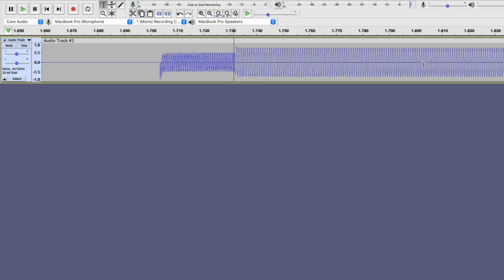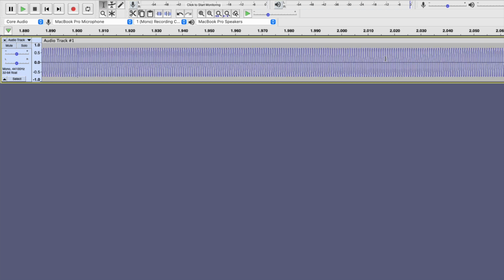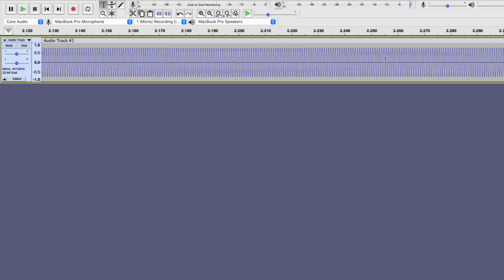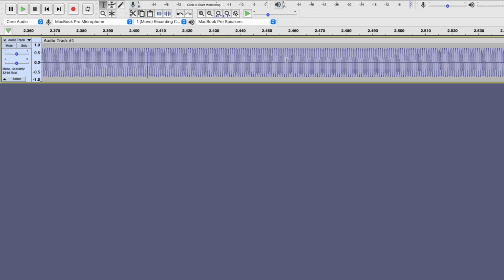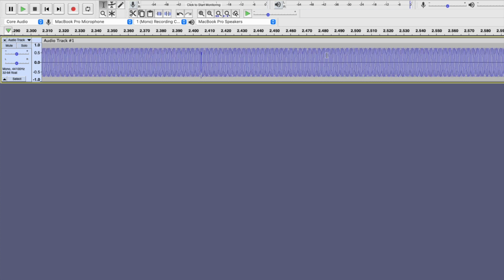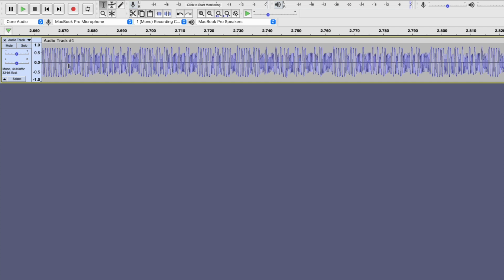Since the saved data from the screen starts out with a lot of zeros, that's what we see for the first long part of the recording. When the text on the screen starts, we see the uniform envelope turn into something a bit more substantial. If we want, we can even start decoding the bits by hand. If we zoom in a bit, we can start manually doing the same thing the receiving computer is doing.